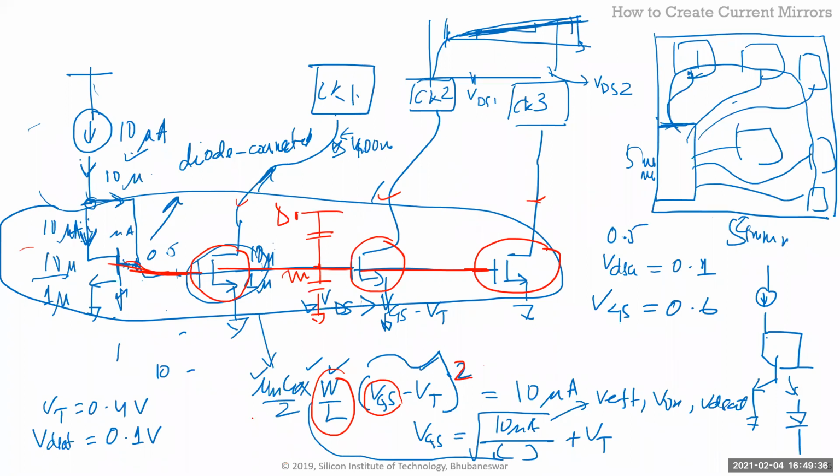So typically we just put all of them together. Now your question is, okay, so we put all of these together in one place, in this band gap. That takes care of the mismatch. Now we start shipping this. So these are long routes right now. So isn't this a problem with coupling? Because now this same inverter here is going to couple to the drain side. Why is it not a problem?